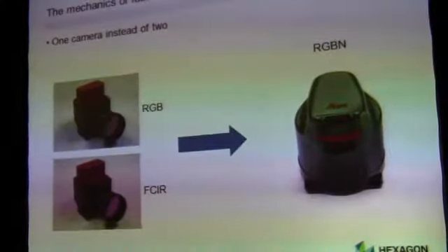But one example where you do merge, and maybe this is a bit far-fetched, but I think it's not, because we thought about it 2.5 years ago: it's a relatively easy feat to bring into the medium format market the RGB sensors with the full-scale infrared sensors to create what we call a multispectral sensor. This is also sensor fusion, because in most cases previously with our RCD105s we had to have two camera heads, with different filters on top. The problem downstream is that you don't have co-registered images. You have an RGB image and a full-scale infrared image, but you can't bring the two together because of course your projection centers are slightly different. So with the RCD30 we brought that together, and the interesting part here is that everything downstream changes.